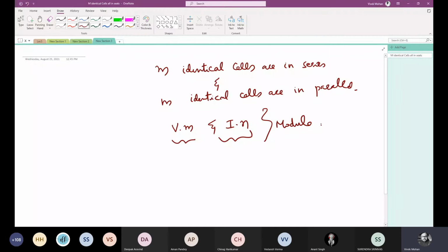Now this is just the PV module. With these PV modules, if we form a PV system, it will have a load that we should feed. An inverter would be there, if the load is AC, to convert the DC power output of the panel to AC. Then if you need to power the load at night also, you have to install a battery, and the charging and discharging of the battery should be controlled.